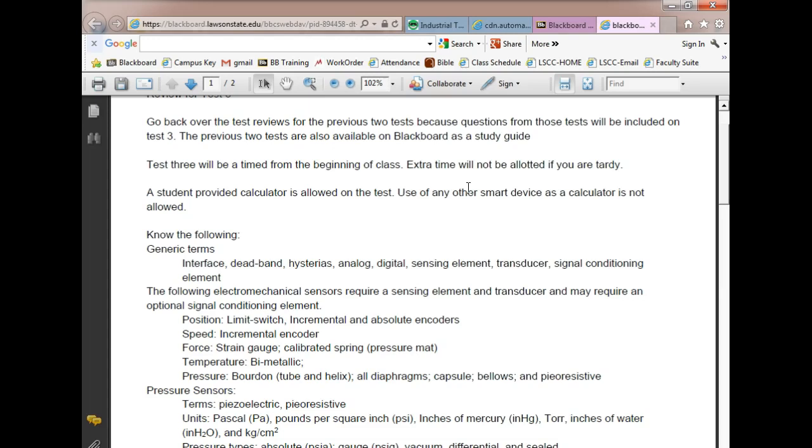You're setting a parameter, so that's the deadband. Some of those sensors you set yourself. With the temperature sensor, we set the deadband, right? Digital sensors, we don't have to worry about it because they energize at a voltage. So they're either on or off, right? Unless we get around what we call the holding current.